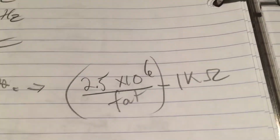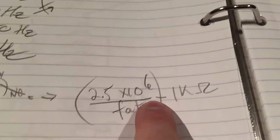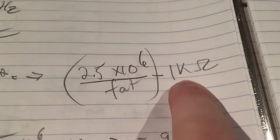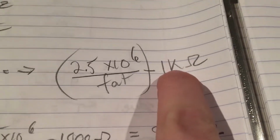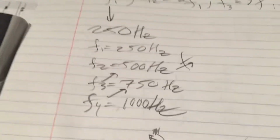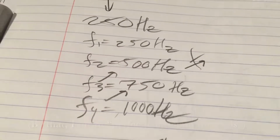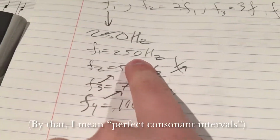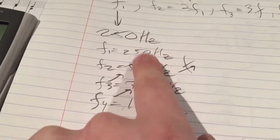Simplifying this equation further, we find that we can divide 2.5 times 10 to the negative 6 by our desired frequency and subtract our 1 kilo ohm resistance, which is fixed for RT. When designing this circuit, I decided to explore different perfect consonances. I decided that my lowest, or supposed root note, would be at 250 hertz.